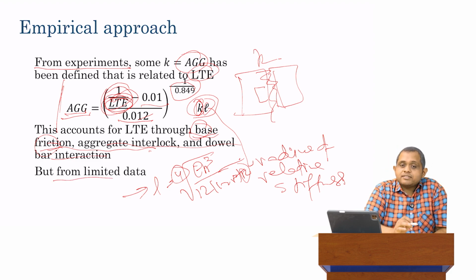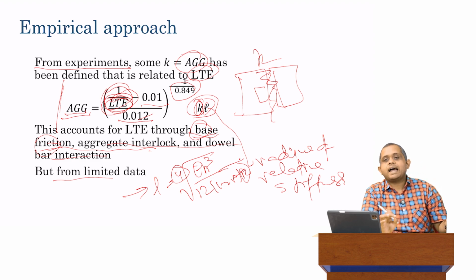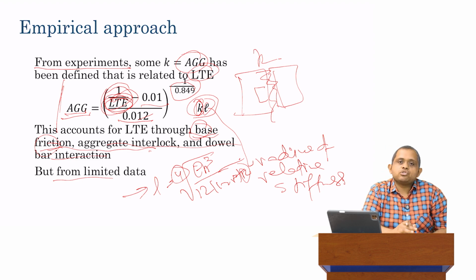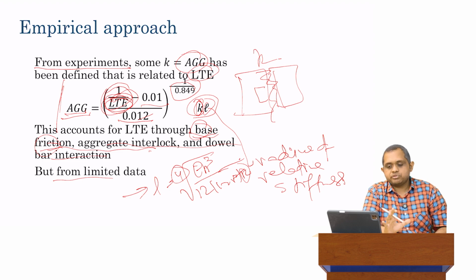In fact, one of the biggest shortcomings of this is that it was specifically created for cases where you had a slab, an aggregate base layer, and then a subgrade, and only certain types of subgrade. And of course, not even to mention issues of temperature and variations in material properties, etc. So it was based on a very, very limited amount of data which was collected. It is still used very widely in literature, you'll see it used in a lot of research papers, but it is an empirical function. It's actually currently being used right now far beyond what it was meant to be used for initially.